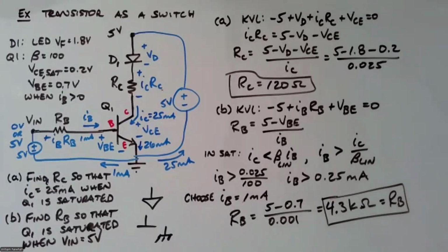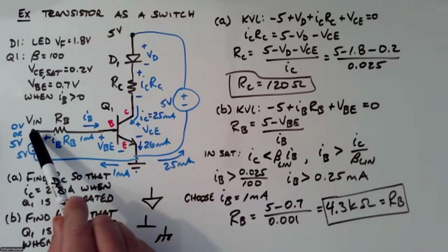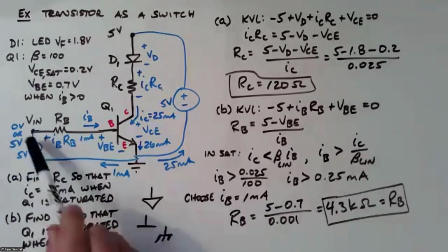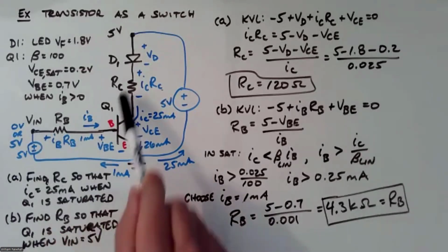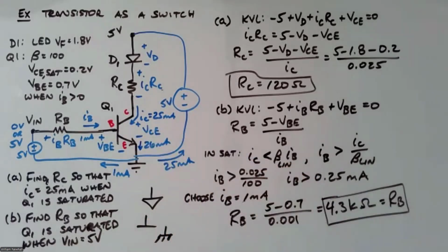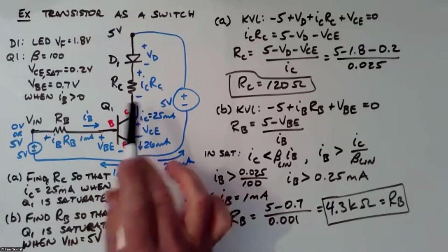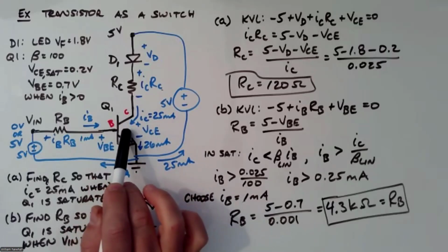Okay. So this is what I wanted you to get out of this class: to be able to control a load electronically, because inevitably at some point in your projects, you're going to run into a microcontroller where you want to control some kind of load. You can use a BJT, bipolar junction transistor, for currents on the order of 100 milliamps, maybe a couple hundred milliamps. I've seen them work up to 500 milliamps. If you're controlling larger currents, like multiple amps, 5 amps, 10 amps, 20 amps for, let's say, a larger motor, you probably want to use a field effect transistor here.